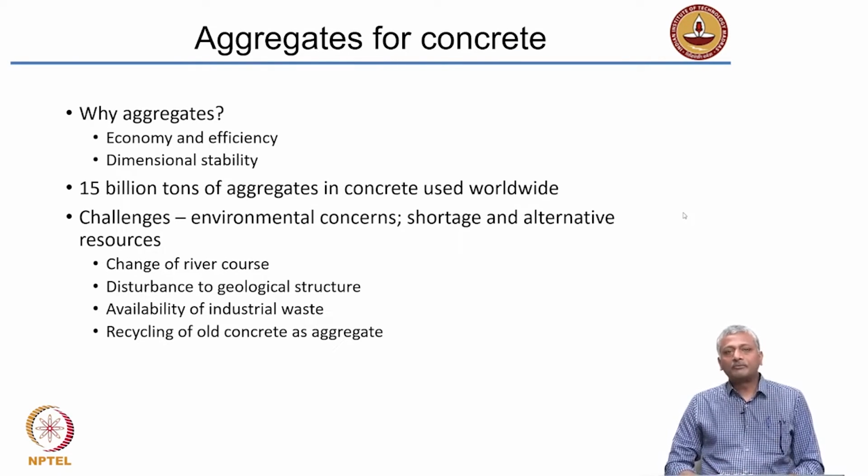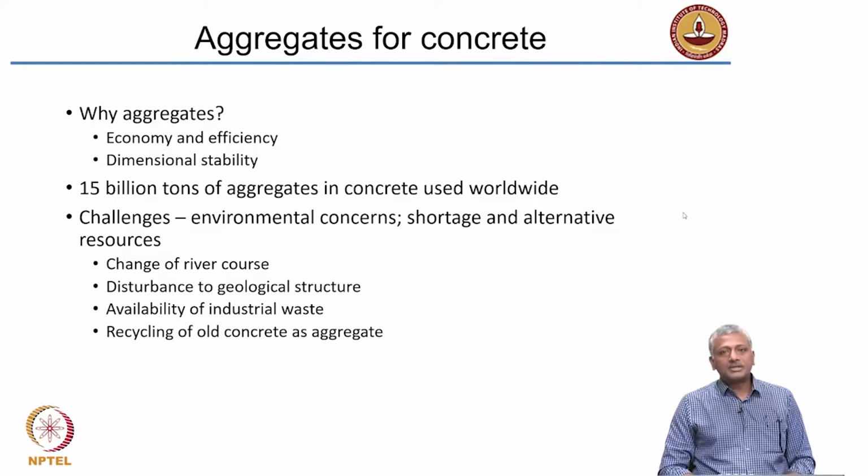The second problem with cement paste is that with time the water dries off, leading to shrinkage of the cement paste, and that will lead to cracking. Now, this is quite common. Shrinkage is a very common phenomenon, especially when you look at soils like clays, right? In the wet season, you'll find they are very slushy and muddy, and when the season changes to a dry season, you see the ground starting to crack, and that's happening because all the water that was retained inside the clay has now been driven out by drying. So shrinkage has happened, leaving behind the cracks. The same thing will happen with cement paste.